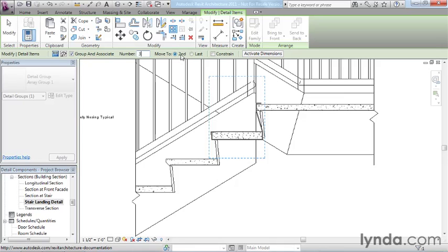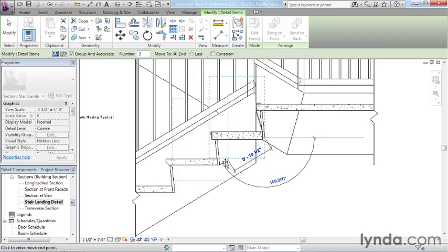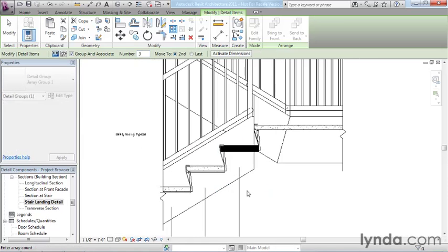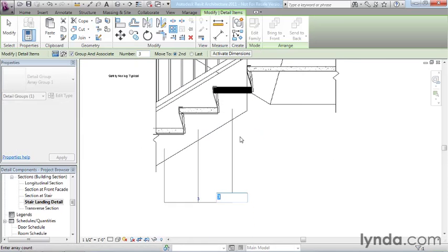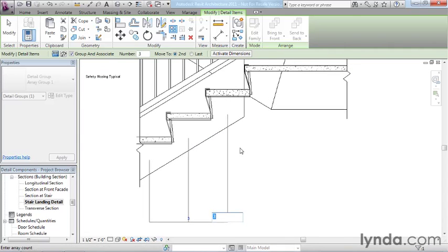In this case, because I'm dealing with stairs of known size, I'm going to go ahead and leave it with the second option. And then my job is to indicate to Revit somehow that spacing that I want to use. And the easiest way to do that in this case is going to be to object snap right here, and then object snap the corresponding point on the next tread. So right there. And what you'll see is, if I zoom out just a touch, the 3 items array in a stair-step fashion, and then this temporary dimension appears down at the bottom.